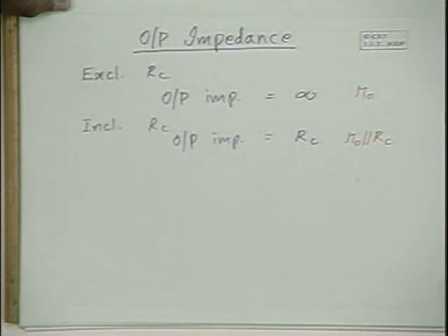Please note that when I discussed the small signal analysis of the amplifier with fixed bias circuit, the equivalent circuit is similar. Therefore, the same analysis holds good here also, where RB is R1 in parallel with R2. Any questions?